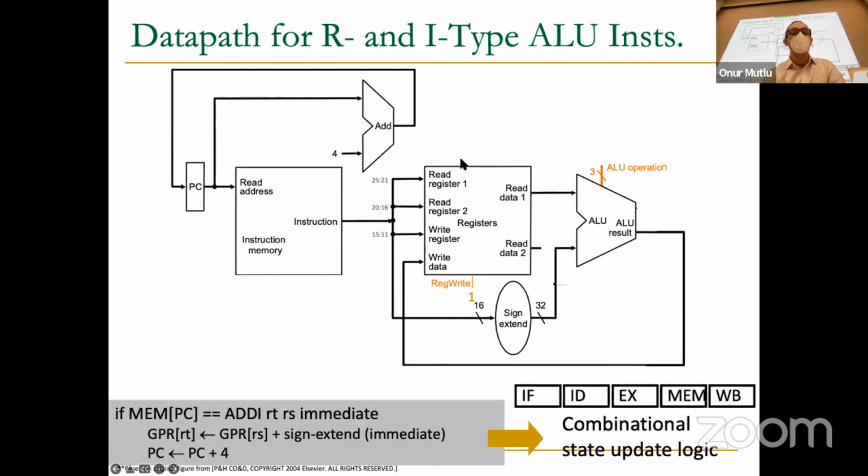So if you're just implementing, what happened? So basically, this was register to register add earlier. We actually had this, but now we need to add a register and an immediate. Everything else is still the same. The different part compared to the register to register add is that you take the source register over here and add it to the sign extended immediate. The sign extended immediate comes from the bottom 16 bits of the instruction.